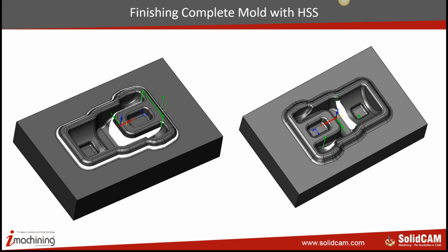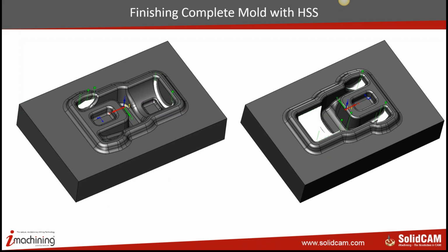Yes, it took about a couple of hours for us to finish this entire part, but the result on the machine was worth looking at, because we had two distinct parts, one completely finished off with HSM and one finished completely with HSS. The result was, I can say, dramatic in terms of finish. So you can see that every portion of the model was picked up individually and machined. I'm going to show you this part also on how we perform this machining.